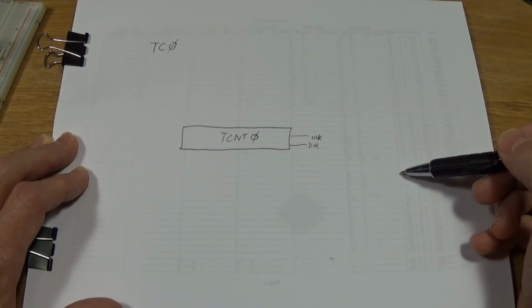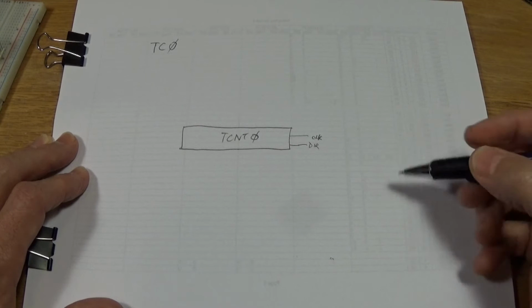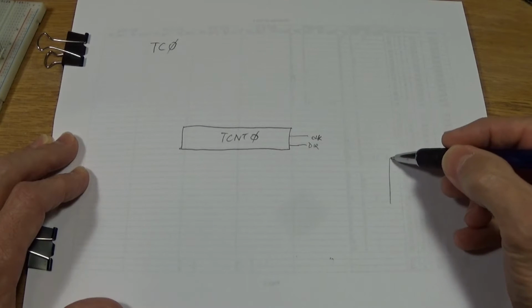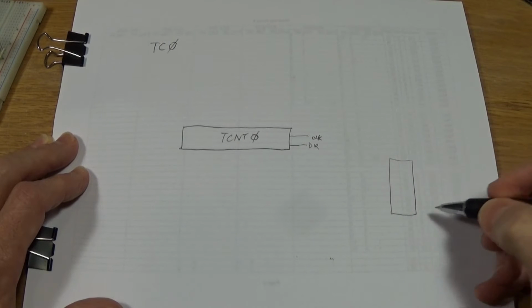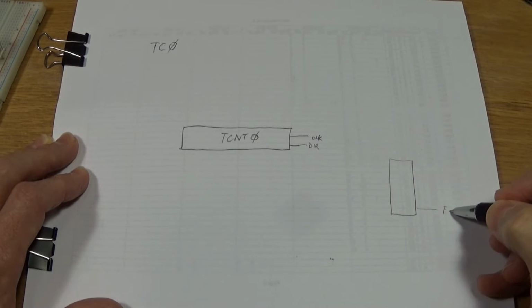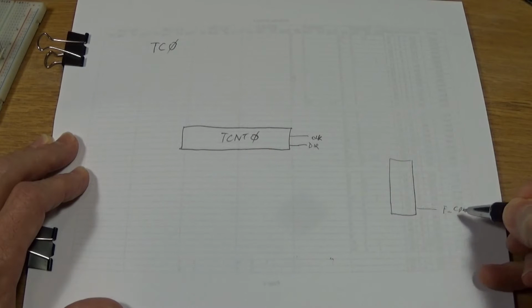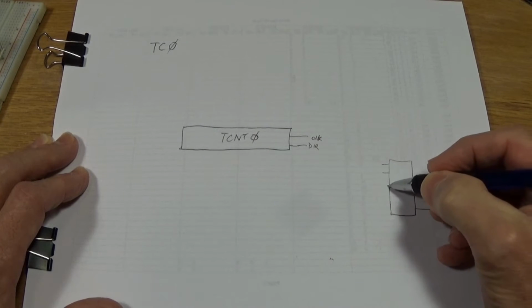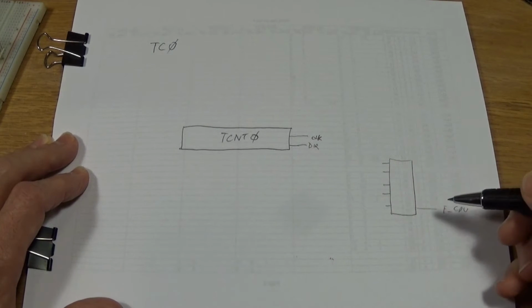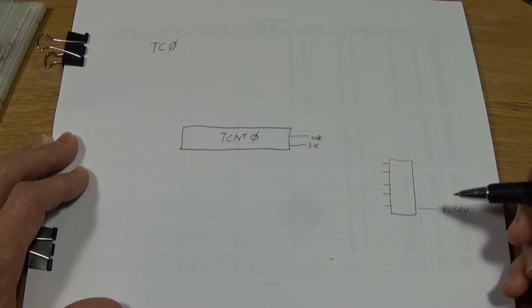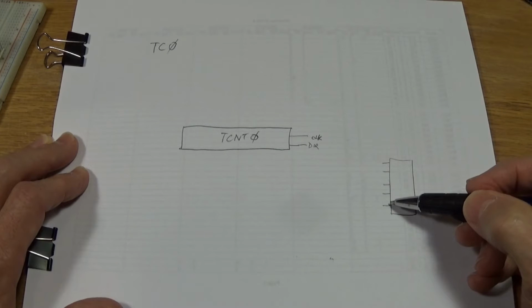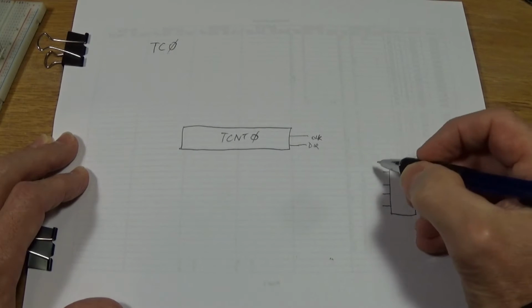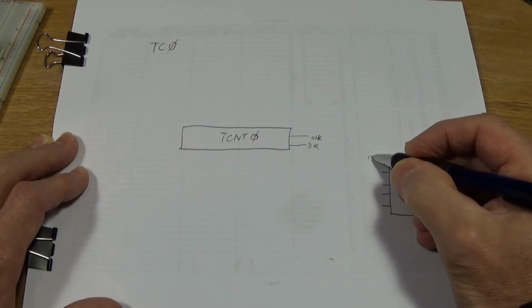You could run it directly from the FCPU, or you could put it into another device that is called a Prescaler. And so FCPU comes in here, and then the Prescaler has a number of taps coming off of it. And what a Prescaler does is just divides by a certain number. And so these taps could be, I can't remember exactly what they are, but I think it goes from divide by 2 to all the way up to divide by 10 to 1024.